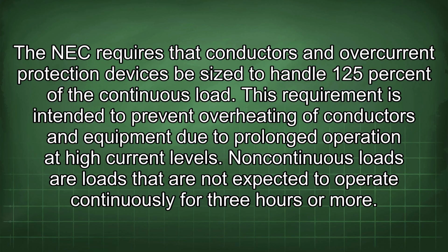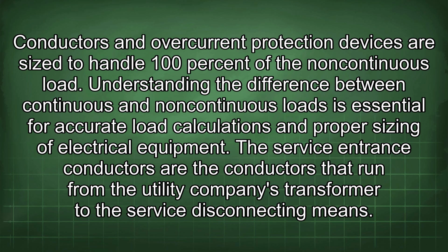Non-continuous loads are loads that are not expected to operate continuously for 3 hours or more. Conductors and overcurrent protection devices are sized to handle 100% of the non-continuous load. Understanding the difference between continuous and non-continuous loads is essential for accurate load calculations and proper sizing of electrical equipment.